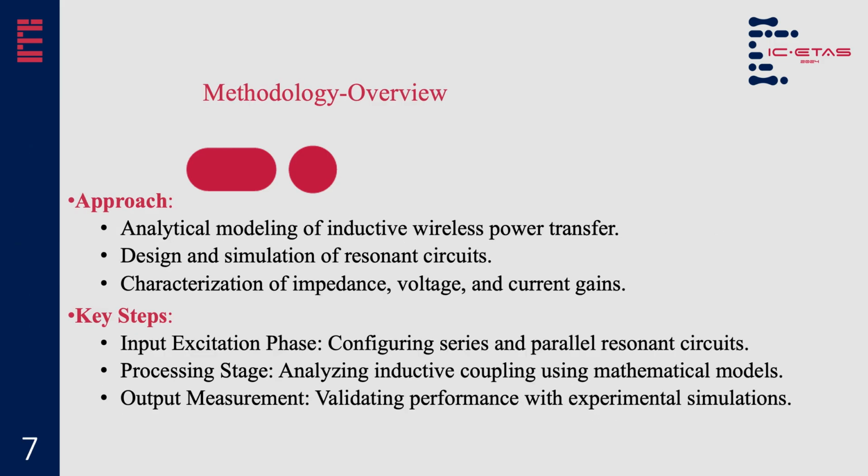Now let's quickly take a look at the methodology we use. Let's look at the approach first, to how these problems were solved. The first one was the analytical modeling of the inductive wireless power transfer. We did the mathematical modeling of the wireless inductive power transfer. The next step in the method was to design and simulate the resonance circuit itself. The third approach was the characterization of impedance, voltage, and current gain. After we design and simulate the resonance circuit, we characterize the impedance, the voltage, and the current gain. Now, here are the key steps that we follow.